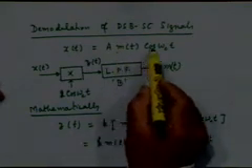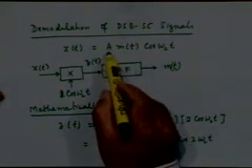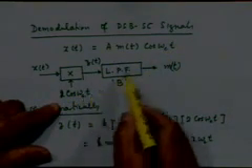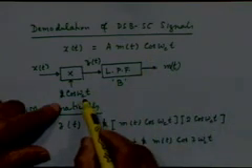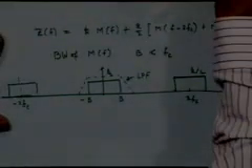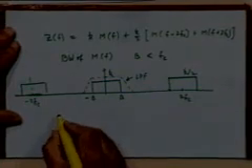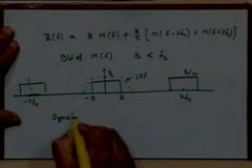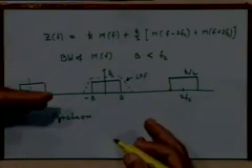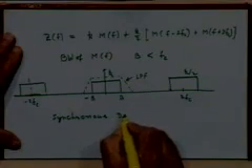The modulation was being done by multiplying m(t) with A cosine omega c t, and we are assuming that a perfect knowledge of frequency and phase of this signal is available at the receiver, right? So that you can multiply it by a local carrier, a replica, and get your demodulated output. So implicit in this demodulation process is the concept of synchronicity between the transmitter carrier, the received carrier, and the local carrier of the receiver, right? So therefore this is also called synchronous demodulation.